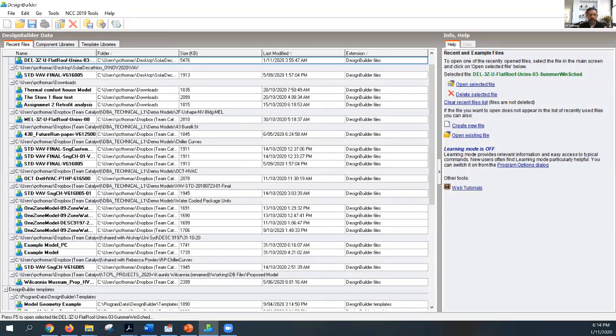There are some 20 or 22 curves for just that one model, but it does allow you to set a design COP, which you can change. So the same curves will modulate the part load performance, but you can set the design COP so that the maximum will be limited to whatever you set.